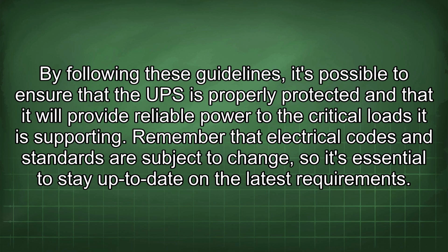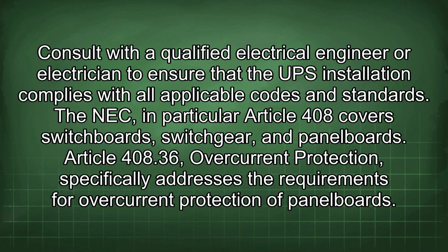Remember that electrical codes and standards are subject to change, so it's essential to stay up to date on the latest requirements. Consult with a qualified electrical engineer or electrician to ensure that the UPS installation complies with all applicable codes and standards. The NEC, in particular Article 408, covers switchboards, switchgear, and panel boards. Article 408.36, Overcurrent protection, specifically addresses the requirements for overcurrent protection of panel boards.